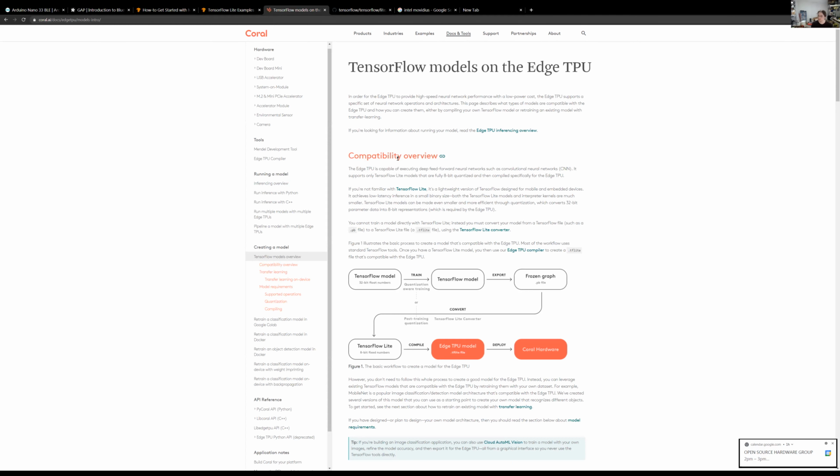But once you get your model defined, you can take that model and slim it down to fit onto either an edge TPU or onto an IoT device. The IoT device is really small and really general purpose, and the edge TPU is a little bit more resource intensive, but allows larger models and a little bit more fidelity. And after that, there's a big leap between that and going into dedicated hardware like a GPU or a dedicated ASIC for machine learning.